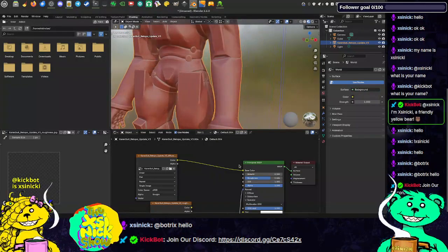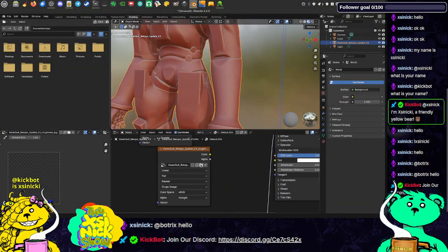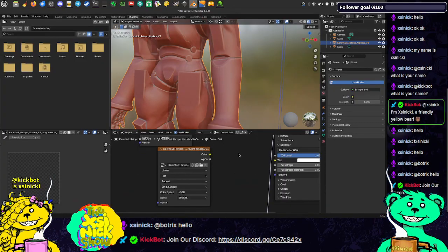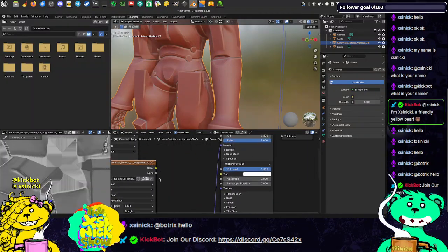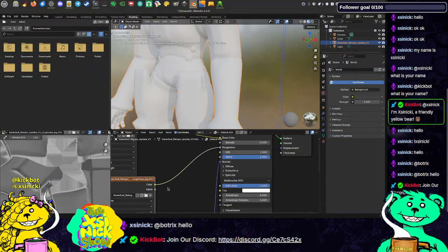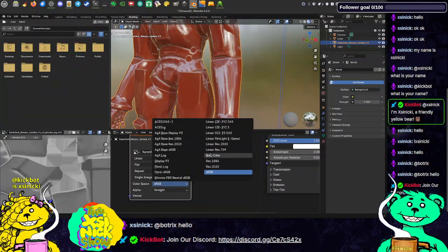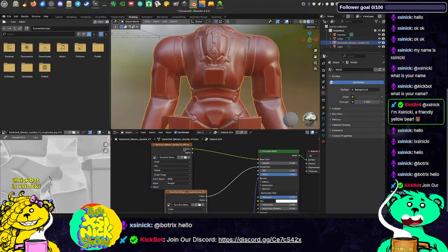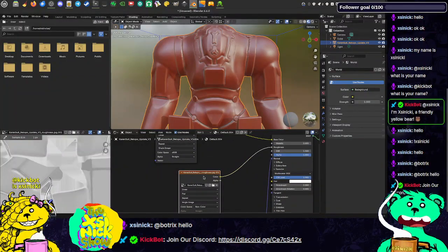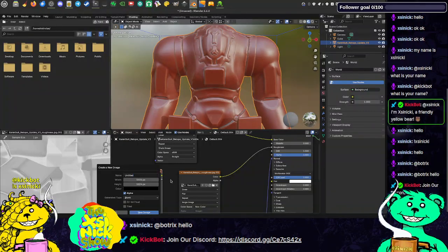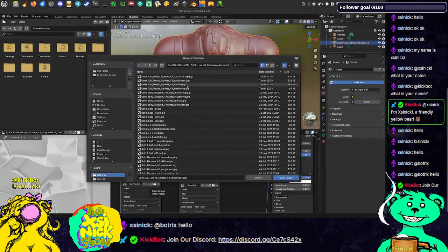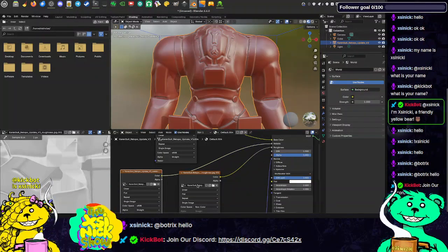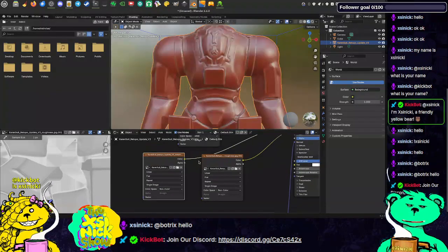Yeah, here we go. Okay, so what's this one? It's supposed to be roughness. Let's grab that. Okay, so we do have a roughness map. There it is. And plug that into roughness. And the roughness map is the same thing. You have to tell it do non-color. Here it is. I think we have a metalness map in here too. Let's go grab that. I'll do the same thing, non-color for that one, that's fine.